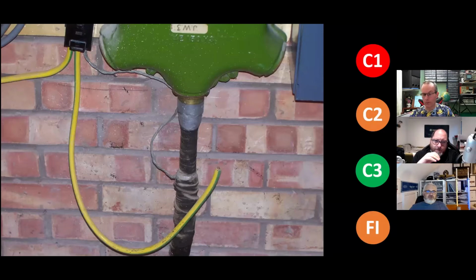It has, and the DNO have gone, sod that, I'm not using that, mate. Why would I use a solid, hard copper cable when it's an old lead that I have to manipulate and sweat a new one on? So they've left that. And in all fairness, if you do an adiabatic on it, it's probably fine.